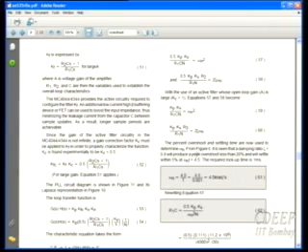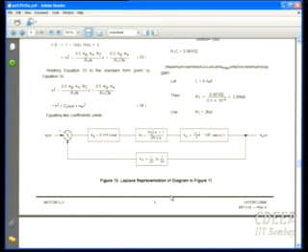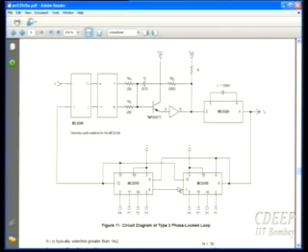Therefore, according to overshoot, deriving zeta, according to settling time, deriving omega n, and therefore choosing values. That's a very interesting example because it is based on discrete ICs and they choose components in such a way they are close to the available discrete components, and this is the loop. It's a very nice example with all values, and this is the final design.